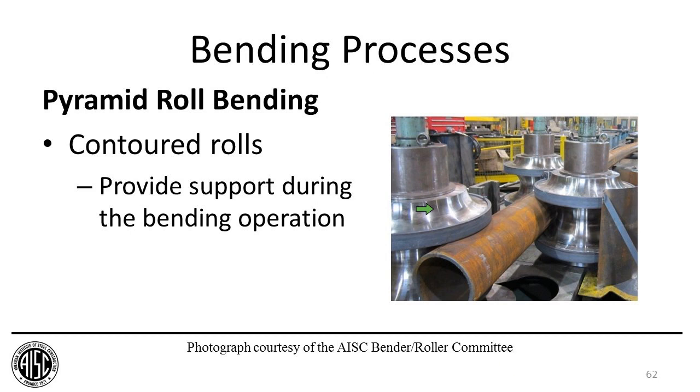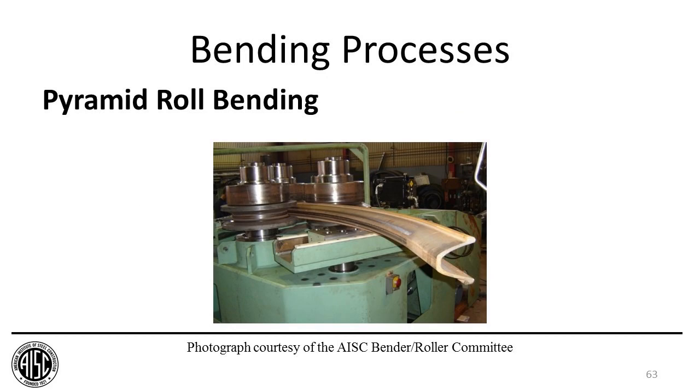On the other hand, the contoured rolls may not be required because it may be a large radius and you may not have much distortion without the contoured rolls. This slide I wanted to put in there has the contoured rolls for this extruded shape. I just kind of wanted to put that in there to quickly show you that essentially you can dream up any shape you're interested in, and you can have contoured rolls for that shape made. It's just a matter of paying the tooling cost, and is it going to pay off if you only have 10 of these members versus 1,000?